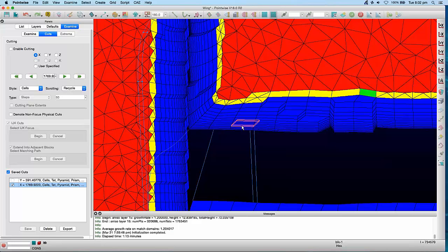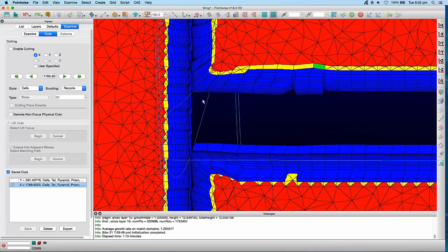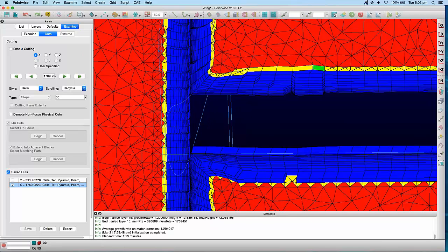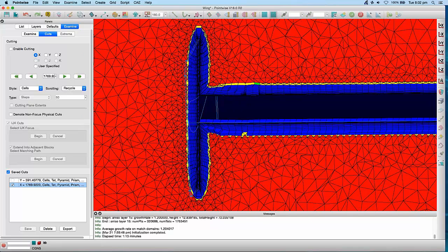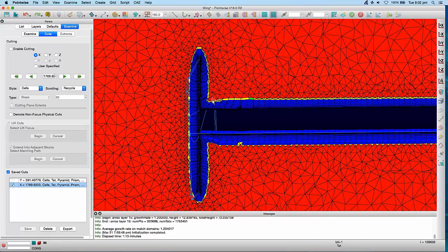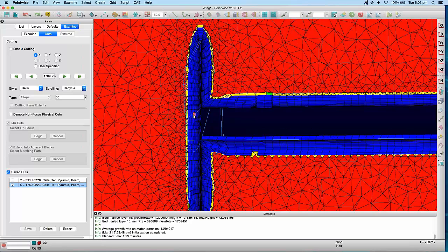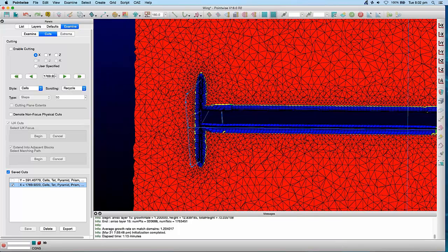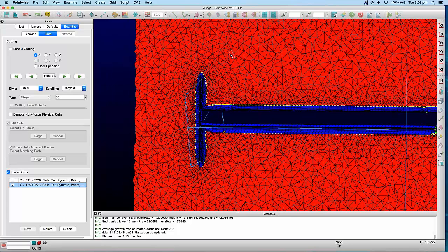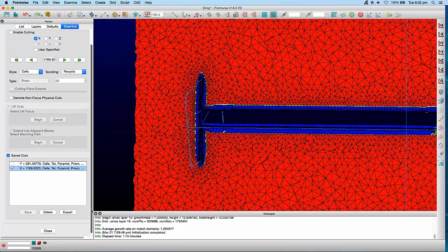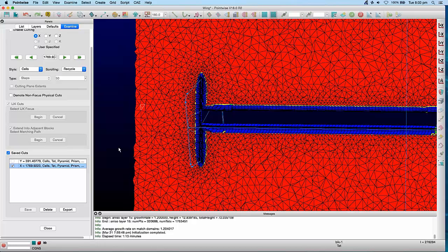Yeah, and I've just mentioned that being able to have a really good boundary layer mesh like this, especially on your end plate area, helps to capture those viscous forces from the vortexes that form between the wing and the end plate there. So really important for getting a really good resolution on the energy inside your vortexes and how they affect your downforce. And what I'm not showing in these cases is we can also put point sources in to then control the downstream resolution to ensure that those vortices that start on the leading edge then resolve rather than dissipate in the mesh being too coarse.